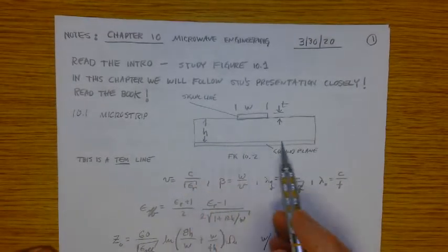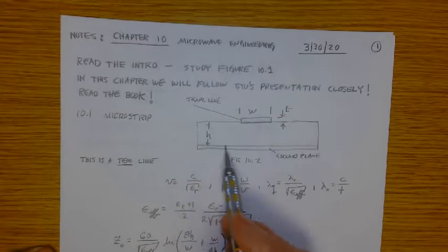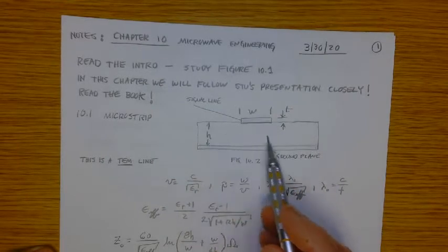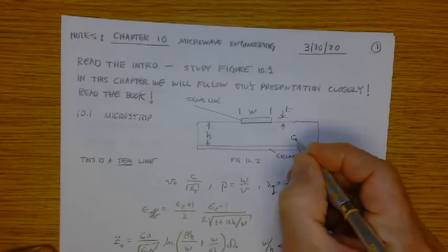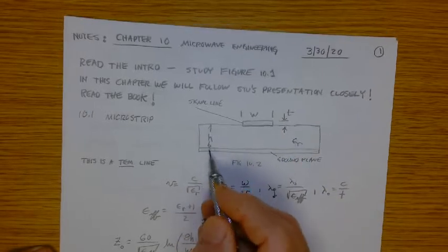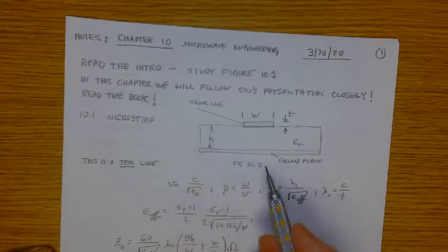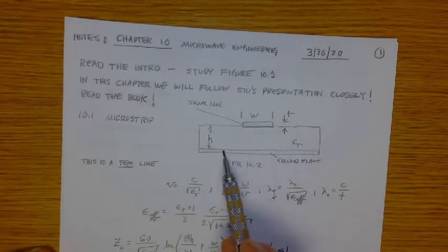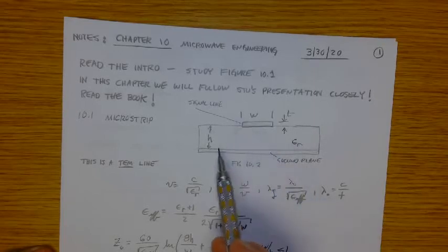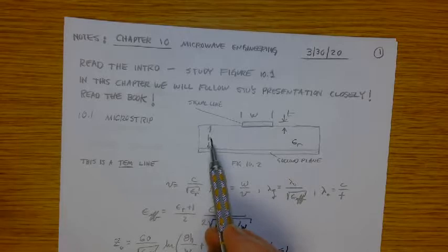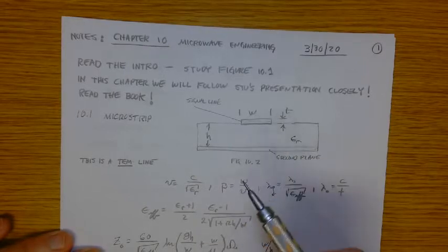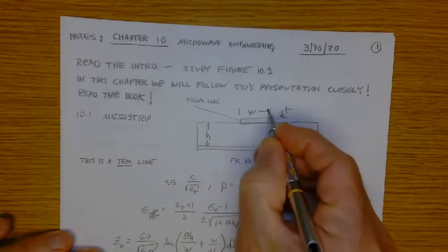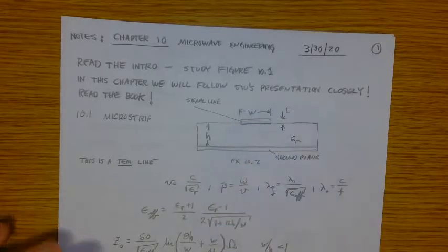Okay, so here's a microstrip. Ground plane, conductor, dielectric, epsilon relative, of some height, h. And so, what are we really interested in? Well, for a given material that we purchase with a given dielectric constant, the height would typically be specified when you buy the material. And then the question will be, what width W do we need to use to get a particular characteristic impedance?